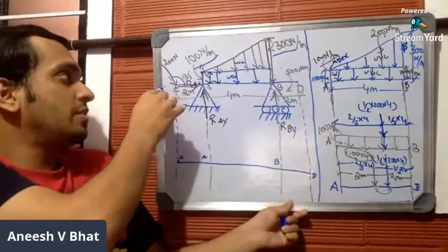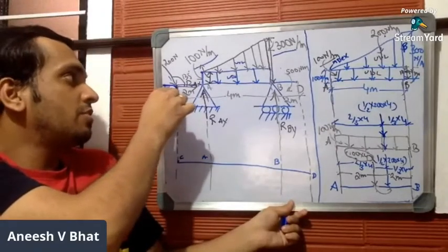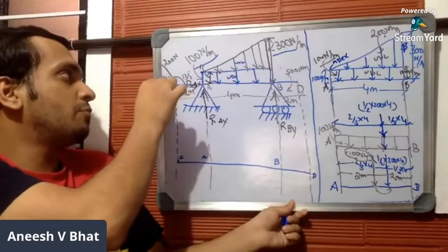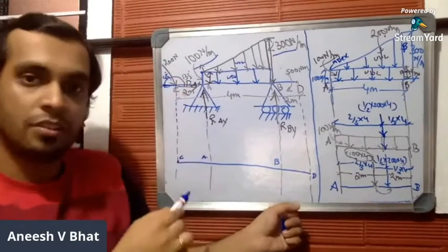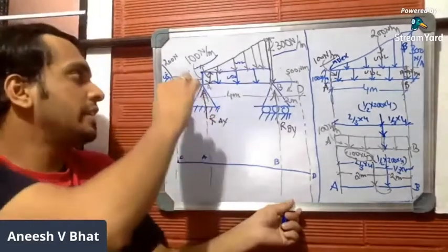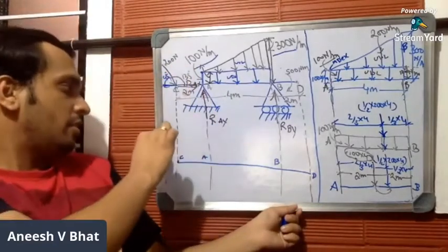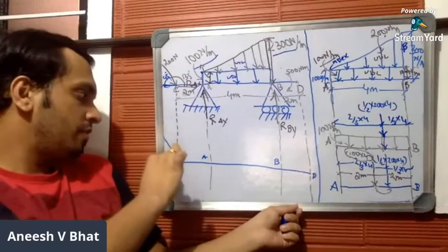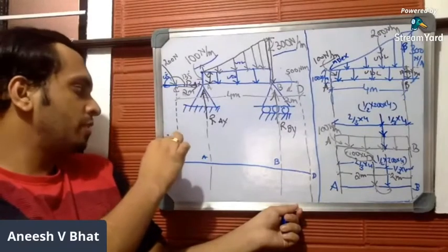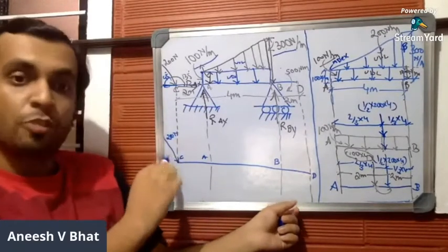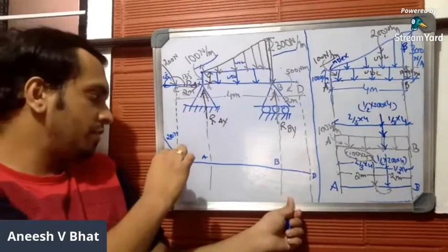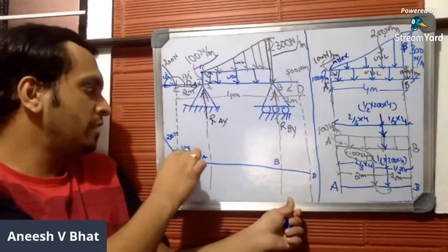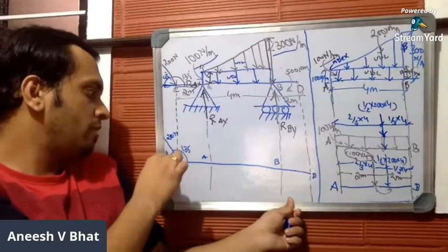See, if I extend this, if I draw an extension line, if this is 135, what would this be? This would be 45, is it not? This angle would be 45. Let me draw it once again. See, if this is the force, 200 newtons, it should be resolved now. That's why I'm drawing it. If this is 135 degrees, this would be 45.